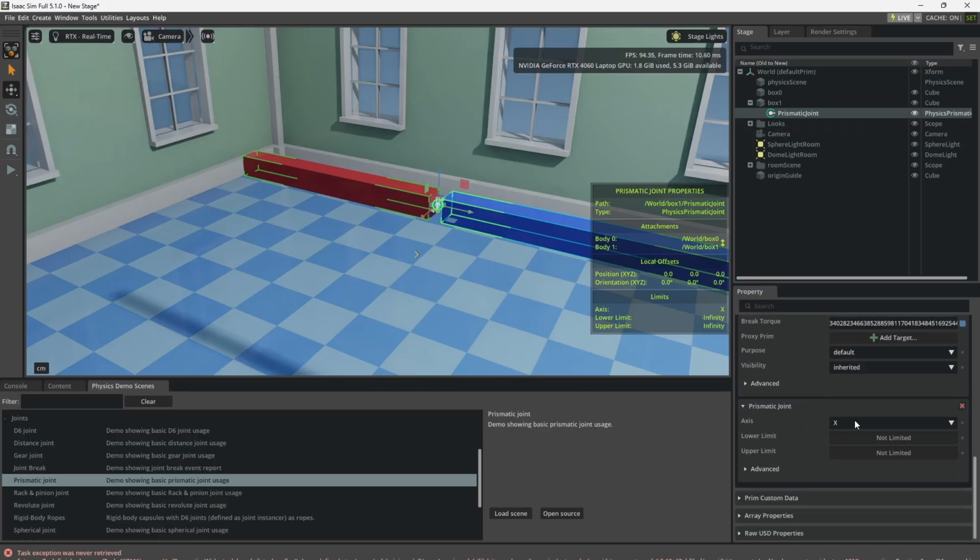Now when we move this here, we can come down and set, I want to have collision enabled, and I'd like the, yeah, let's keep the x-axis and set the lower limit to -50, since that's what it was. And the upper limit to 50. There we go. Whoops, I'm using the wrong axis. I think I want Y. There we go.